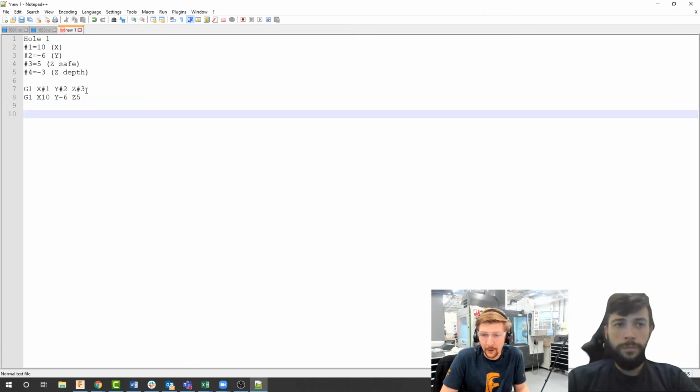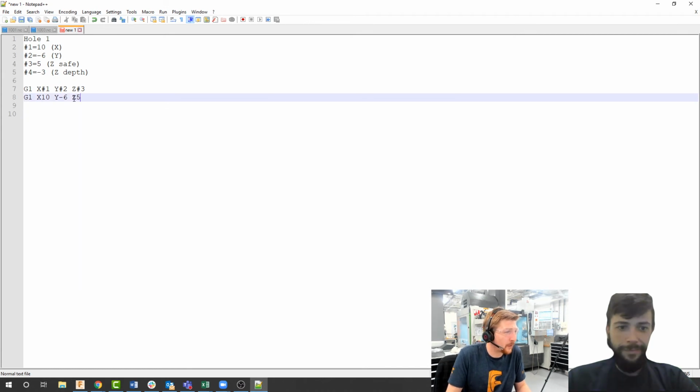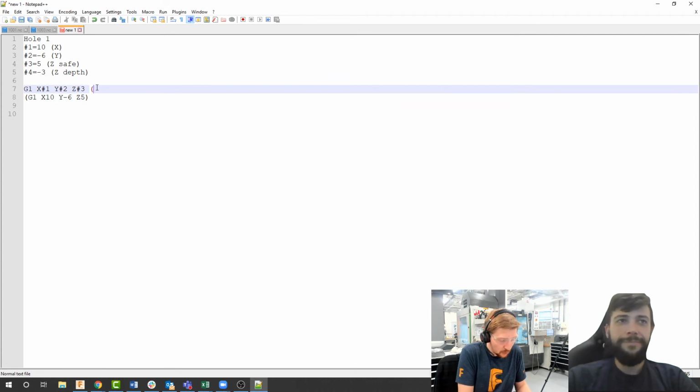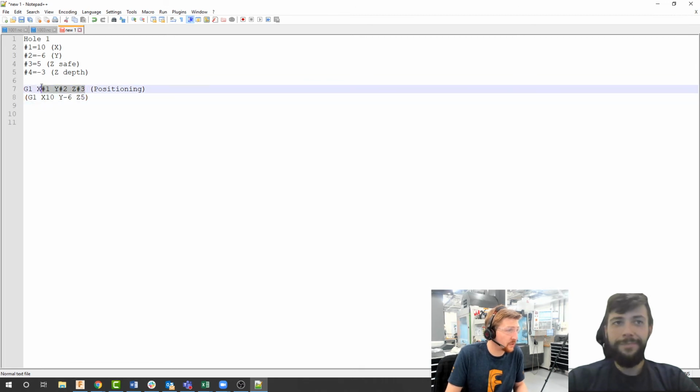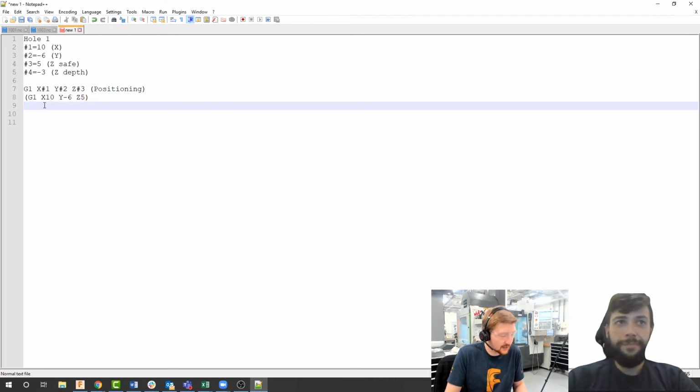I hope you are. Again, I never thought I'd be sitting here hand typing out NC code on a live stream, but that's the way the world takes you. So let's put that in brackets, because that was just our translation of what that would mean. That's going to be my pre-positioning move, positioning over the hole, and then I'm going to do my drilling cycle. I want to do exactly the same as that, but then go to hash 4, and that's going to be my drill.